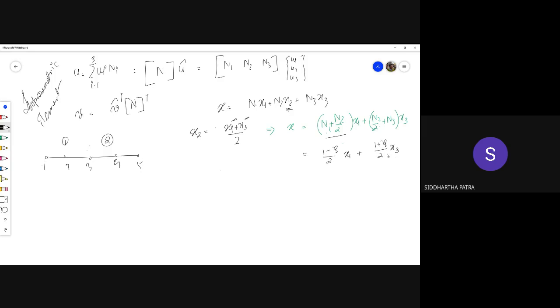Now, which basically means dx d xi is just the same thing as before, which is element length divided by 2, and now it comes to getting u prime, which is also the strain, which is B times u hat, where B is del N. So B is the matrix of individual shape function derivatives with respect to x coordinate.